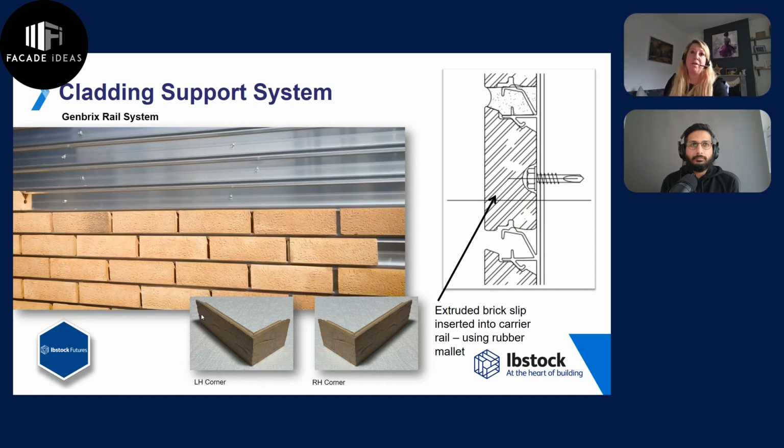You can see there the profile of the slips. The difference with these is that these brick slips that are accepted on this particular system are extruded clay tile slips. So they're extruded in exactly the same profile that you can see there. And how these are installed is a little bit different too. What they do is the bottom of the slip is engaged with that bottom track, and then they are malleted in place, so they're kind of punched into place, and they have a little sacrificial ledge that ensures this is very tightly and snugly mechanically fixed into position.